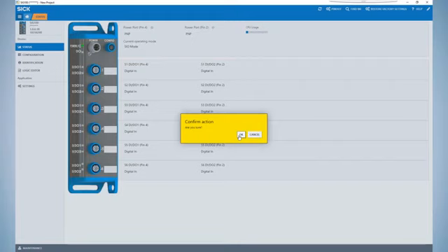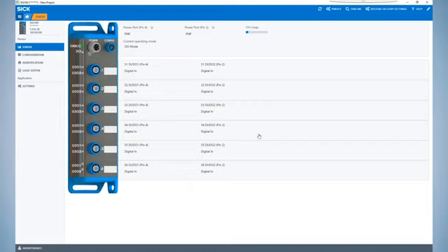A Confirm Action dialog box will appear to double check that you want to restore factory defaults. Any setting currently stored in the device is overwritten if OK is clicked. After clicking OK, a success box will appear indicating that the connected SIG100 has been restored to factory default settings. Click OK to go back to navigating the user interface.